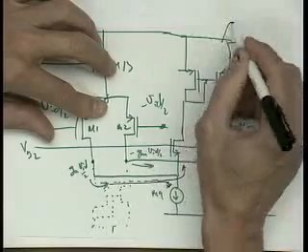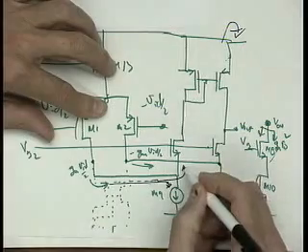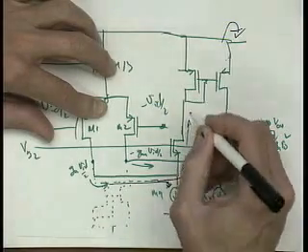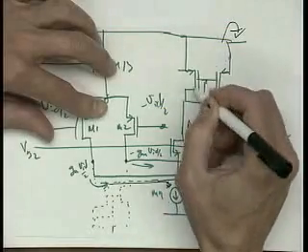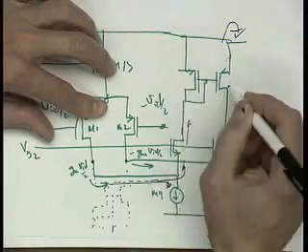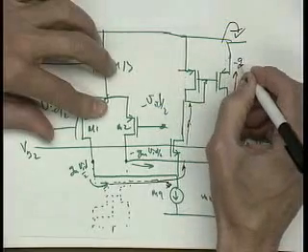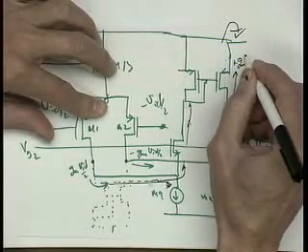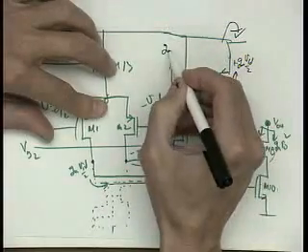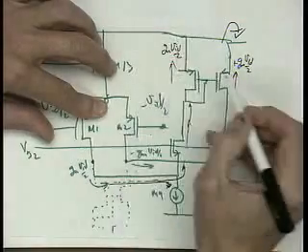And this is all small signal now, right? We're trying to get to a ground here. So this goes up. This goes up through this cascode. That's fine. So it keeps going up there. Then it hits this diode-connected transistor, which is actually just this current source load. So that's going to get mirrored over here. So we see a minus gm times Vn differential over 2. This is plus gm Vn differential over 2. So it goes here, goes up through here, and gets mirrored over to here.